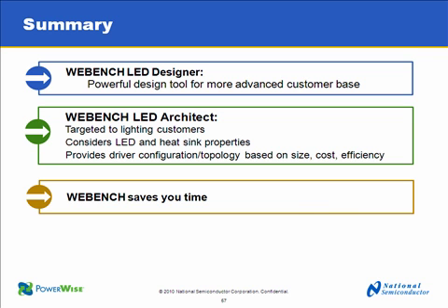It considers the LED behavior over temperature and current, and also the heatsink properties and the heatsink that's required. It provides the driver configuration and topology, so you can look at different topologies and do cost-benefit trade-offs based on size, cost, and efficiency. Overall, hopefully what we've seen today is that WEBENCH saves you time.